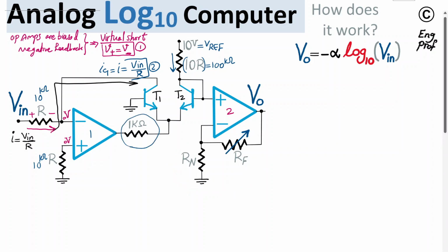This 1 kilo ohm resistor at the output of op amp 1 is for a practical reason, to increase the stability of the circuit, because it's generally not a good idea to apply the fast moving output voltage of the op amp directly to the emitter, which is then directly controlling the VBE of the transistor that is exponentially affecting the current. So it's not a good idea. That's why we usually have this relatively small resistor there as an enforcer of stability. Alright, so that's the only reason for that.